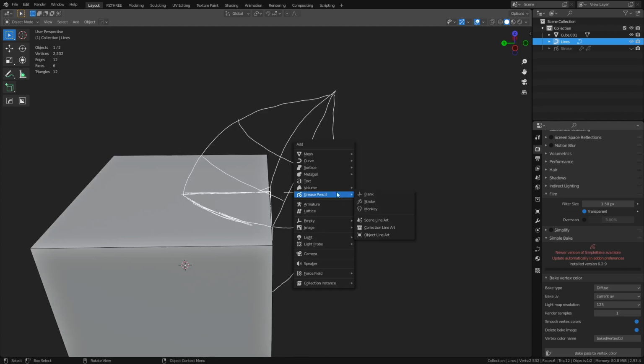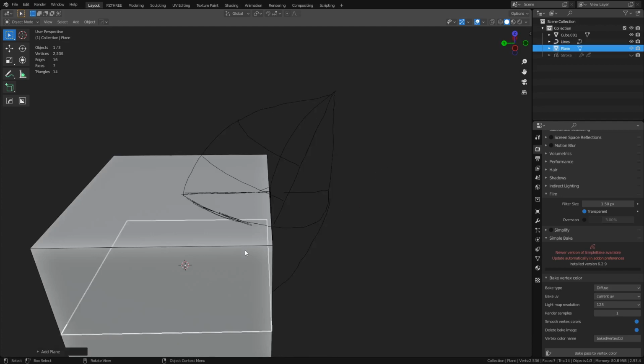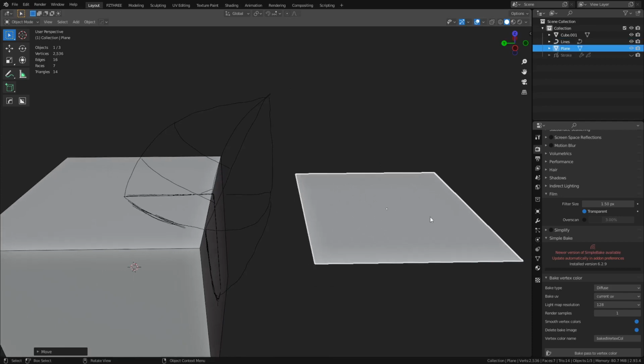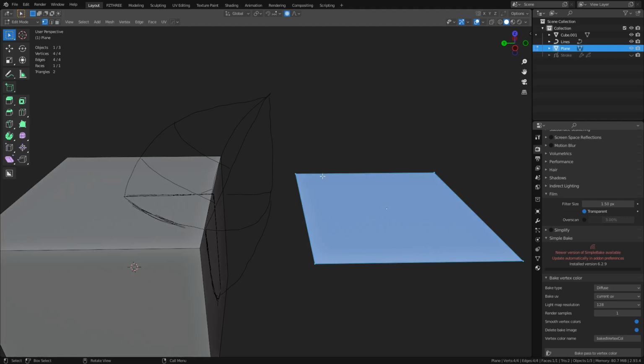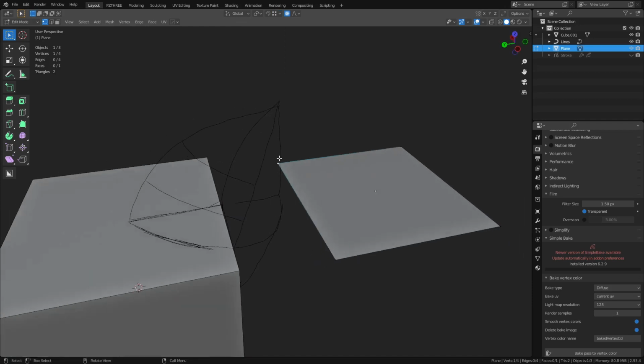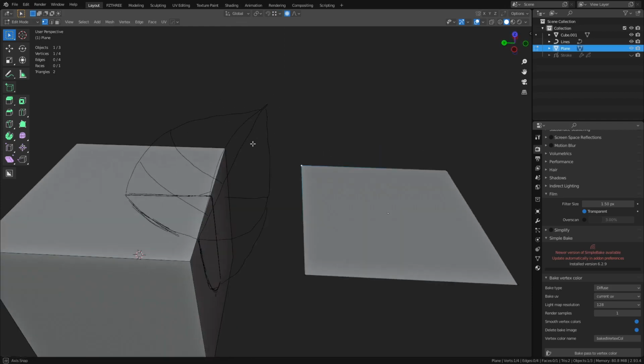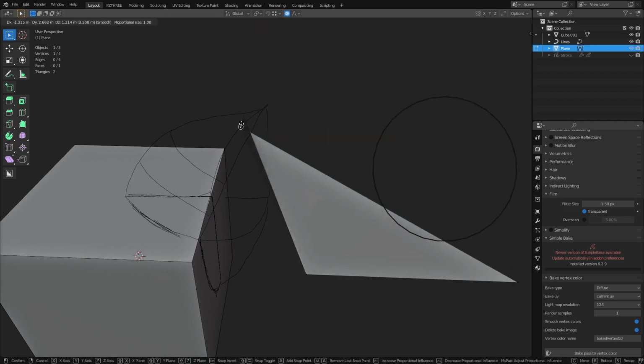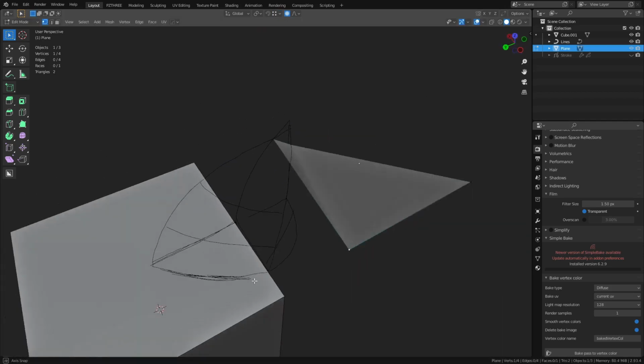So now we can create a mesh plane, and kind of like doing a regular standard retopology workflow, you can use this plane and snap to this object. So we'll go into edit mode. I'm going to turn snap system from increment to vertex. You don't really need to change anything else. You can use each one of these vertices and snap it to this. So press G, hold control, and you can snap. Just that quick, and you're pretty much doing a retopo on this.